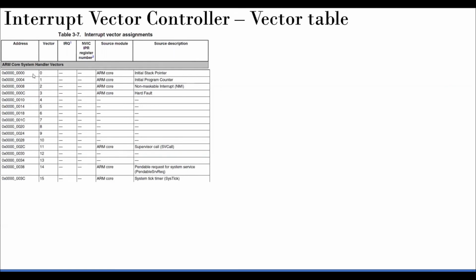So each location is 8 bits, so you need 4 locations. That is why the address points to 4 here. And then here you have the program counter location. That is what it is. Typically when you see the Keil microvision, if you remember, some of you remember that, you will see a reset vector here. So that reset vector or reset handler address will be here. So it will go and execute that particular address or code at that particular address, and that's it.